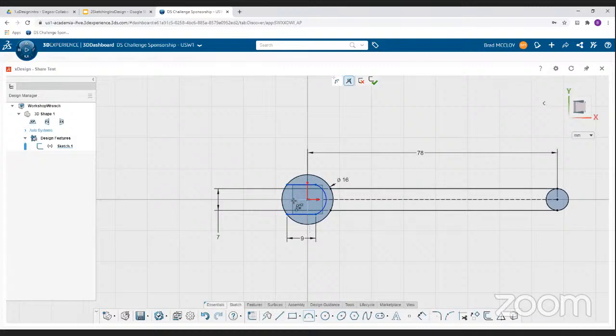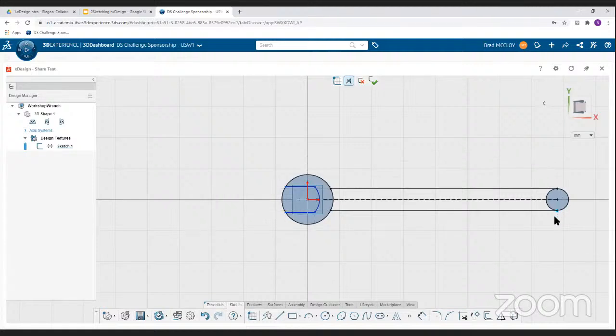So you can see there's a lot of blue in here still, so it's not fully defined yet. Often, if it's not fully defined and I'm not sure why, what you can do, you escape out, grab one of the endpoints, and start moving around, and you'll see, oh, we didn't say how wide this has to be. If it's not fully defined, you're allowed to drag it. If it is fully defined, when I drag it, nothing happens because everything's fully defined and related with this one.